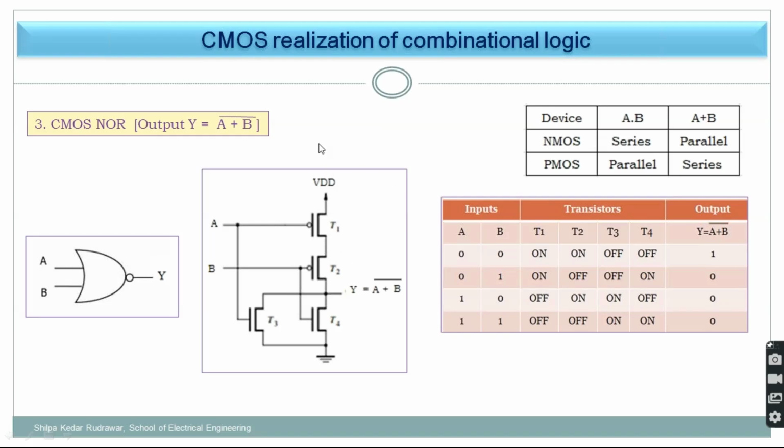Okay, so here is how to recognize what diagram you have drawn. Suppose this is given and you have drawn this diagram. PMOS will be in the pull-up network and NMOS will be in the pull-down network. The pull-up network has PMOS devices, which might be connected in series, parallel, or a combination. Again, NMOS are connected in series, parallel, or any combination. PMOS should always be connected between VDD and the output, and NMOS between the output and ground, that is VSS. All the inputs are connected together and the output is taken in between the PMOS and NMOS circuitry, at the intersection of the pull-up and pull-down networks.